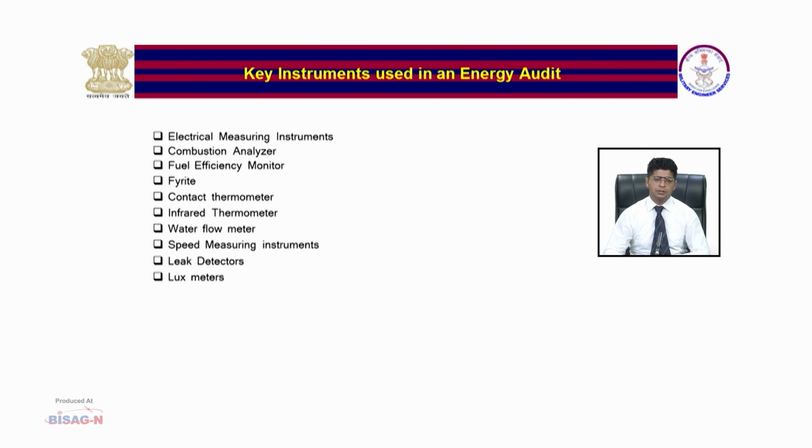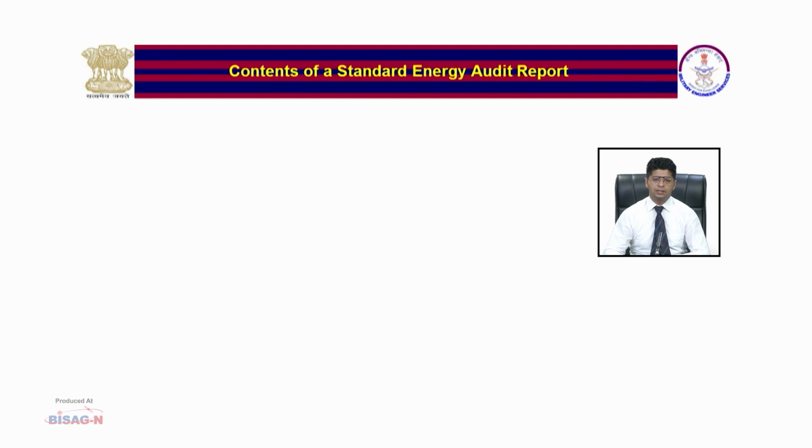meters. Finally, after conducting the exercise of energy audit, we need an energy audit report in a standard format. The energy audit report is required to highlight the details of energy consumption, the energy cost, major energy consumption areas, performance of various types of equipment, and suggested energy saving methods of energy conservation, installation cost, and their payback period.